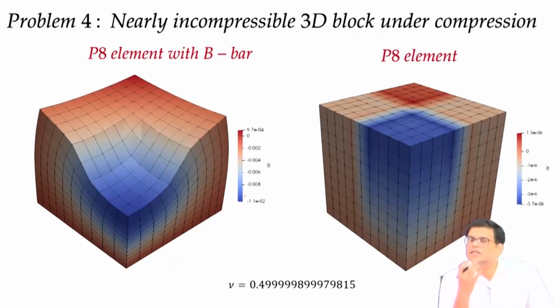From displacement we get strain, then we multiply with the constitutive relation to get the stress. But in numerical simulation, instead of considering stress or strain as derived quantities, we interpolate them and then solve the finite element problem, which gives a mixed formulation involving two or more variables.